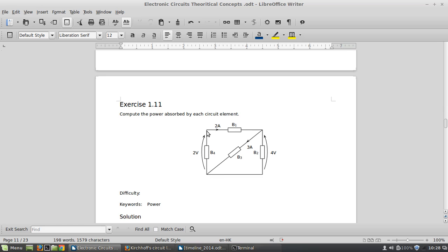So this voltage will be the same as this voltage, you can see, because if you check out the loop here, if you use a KVL loop here, you can see that in this loop there are just two elements. Alright, so this loop's condition is satisfied, and this voltage will be the same as this voltage, and after knowing the voltage you already know the current and you find the power respectively here.